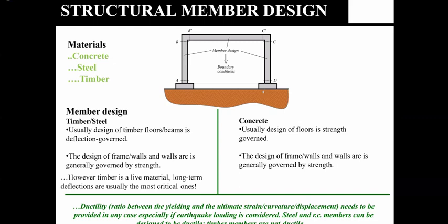When I say design, what we mean is basically arriving at sizes that can withstand the probable loads that can be experienced during its lifespan. At the same time, you don't experience unintended vibrations or deflections, right? So basically, we divide our structural design into two limit states. One is ultimate limit state, which is governed by strength, and we also design for serviceability limit states, right? Where we check for deformations and deflections and vibrations, right?